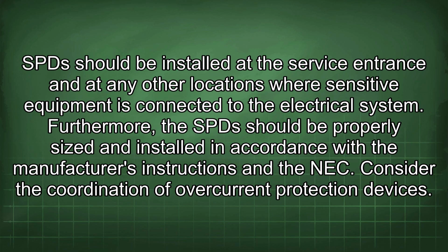SPDs should be installed at the service entrance and at any other locations where sensitive equipment is connected to the electrical system. Furthermore, the SPD should be properly sized and installed in accordance with the manufacturer's instructions and the NEC. Consider the coordination of overcurrent protection devices.